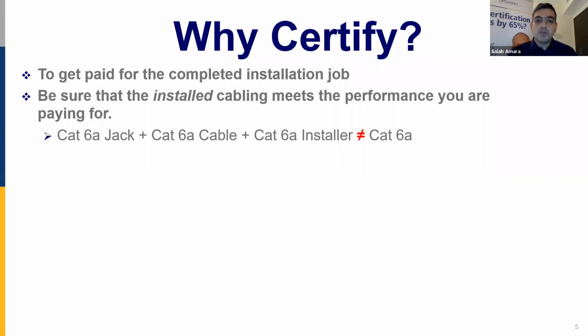It's very important because if I want to have a Cat 6A installation in the field, I need to make sure that the Cat 6A jack is certified, the Cat 6A cable is certified, and as well we need to certify your installation job, which you did in the field. And the only way to do it is to test the installation with our tester in the field.